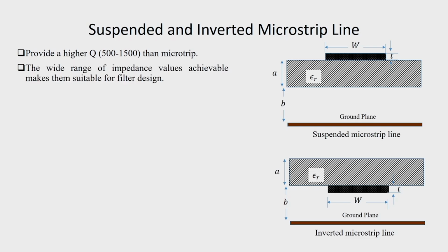The wide range of impedance values achievable makes them suitable for filter design. So, suspended microstrip line and inverted microstrip lines are used in filter design.